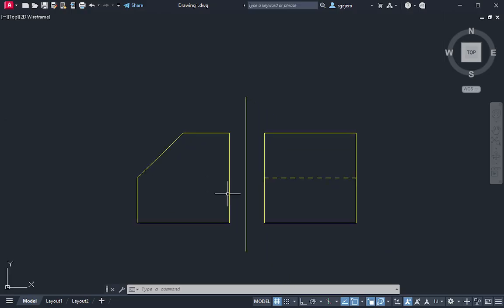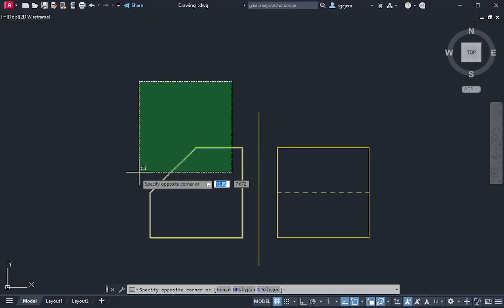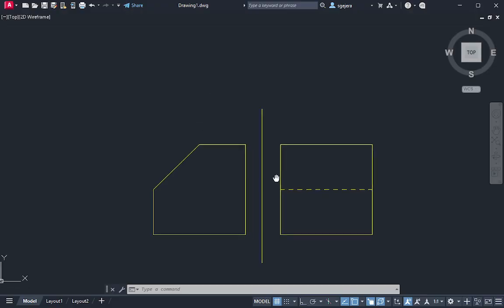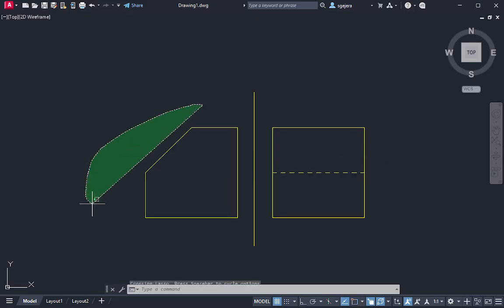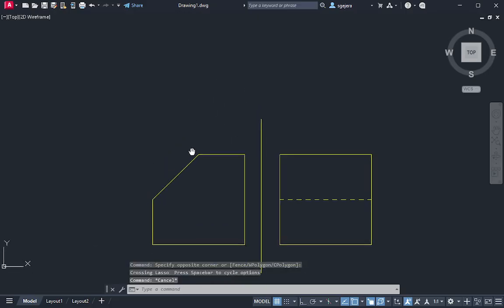Now, how do we look at the inclined plane? Ano yung appropriate na auxiliary reference plane? Sa tingin nyo? We're looking at true sizes. Paano natin ina-expose ang true size ng isang plane? Gagawa tayo ng isang plane that is parallel to, hindi nyo na maalala. Edge view, tama. So, alin yung edge view ng inclined plane? It's this view right here, no? Tama? It shows the edge view. So, ang gagawin lang natin is, we just want to show the edge view.